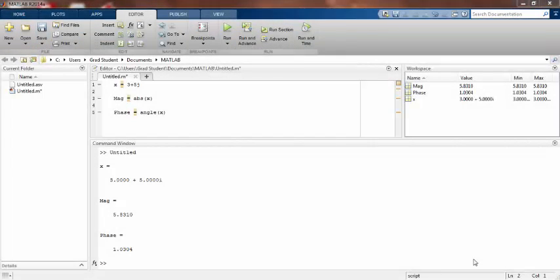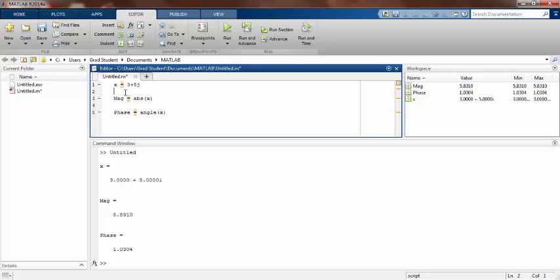Another useful tool we can use in MATLAB is the run section function. Sometimes you will write a script file but then want to run just one portion of it. To accomplish this, you have to divide your code into sections using two percent signs, like what's used to make a comment. So let's add a section to our script file after declaring a complex variable x. So I'll just add another line and then add two percent signs.